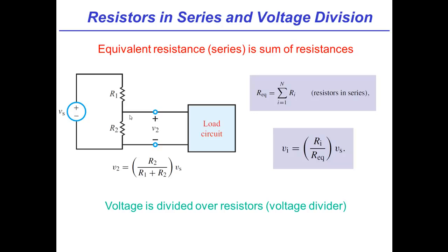Okay, so Michel gave you a hint. He said, let's think about a KVL. So let's ignore this part of the circuit for now, the load circuit. Let's just focus on this loop. What's the current through that loop? So the current through that loop must be Vs divided by R1 plus R2. That's right. So we know the current through the loop.